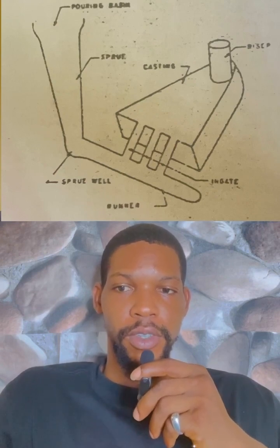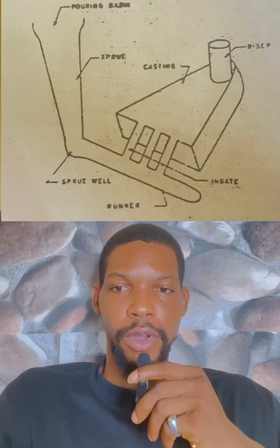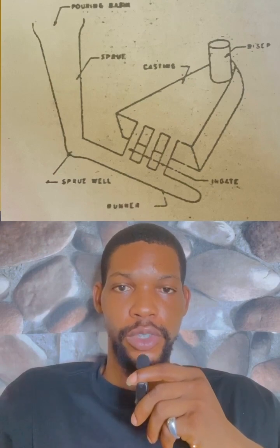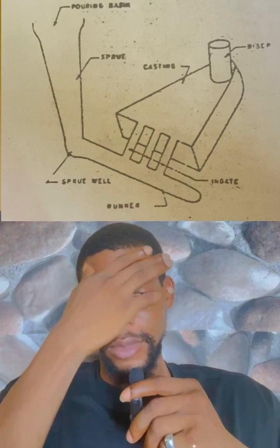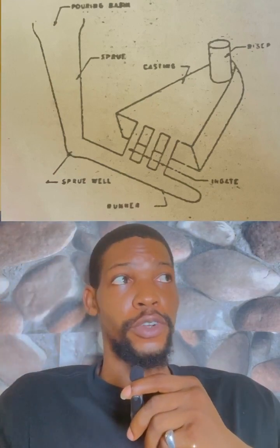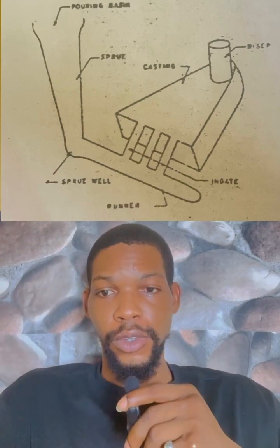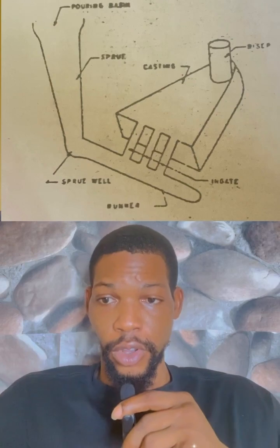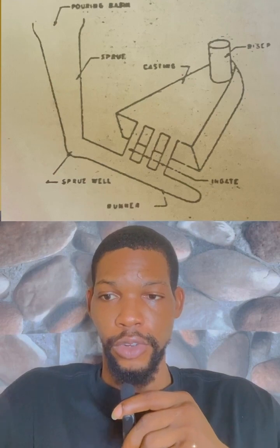turbulence is excessive, aspiration in the mold gate will occur, which will oxidize the molten metal. The oxide so formed separates more or less completely from the melt and forms a dross, which is an impurity in your non-ferrous castings. So dross is the impurity you get in non-ferrous casting, while in ferrous castings you get slag. So to pick up dross or slag, the gating system must incorporate slag or dross traps.